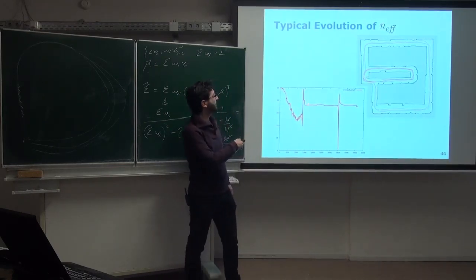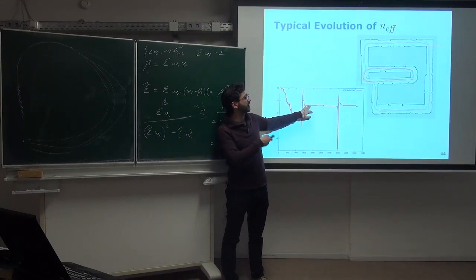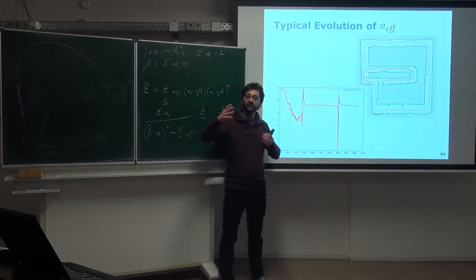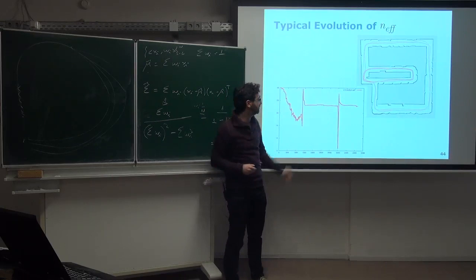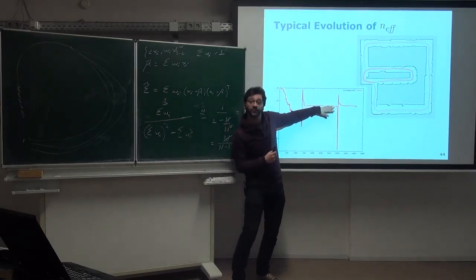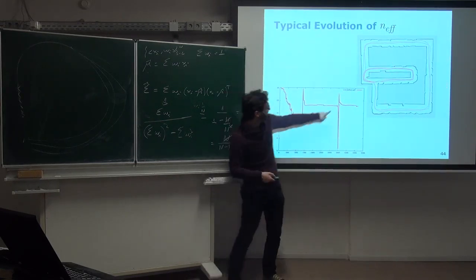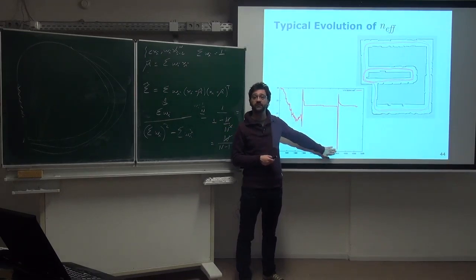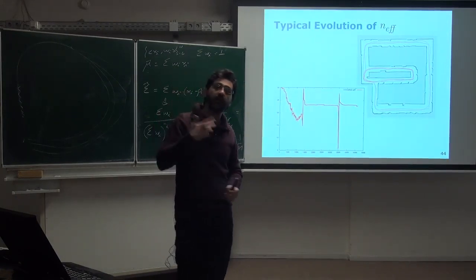And then you go around again, and the robot is in a place which he has already seen a bit. So when he does scan matching around this loop for a while, it is always very well aligned, because this is a part of the environment he already has, and it's always aligning with the environment. So the difference in the weights is very small. That's why they keep being almost the same. And then at some point it goes around again and reaches here, and you see there is a huge drop again because resampling comes into play. Okay, and again.